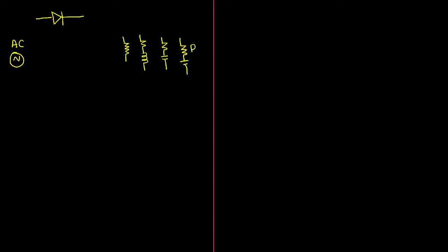What is the difference? E is a kind of battery. Here we are ignoring the effect of the inductor in the RE load. So these are the types of load that we are considering on the output side: R load, RL load, RC load, RE load, and RLE load. When we connect these different loads at the output side, how does the diode do the rectification process?